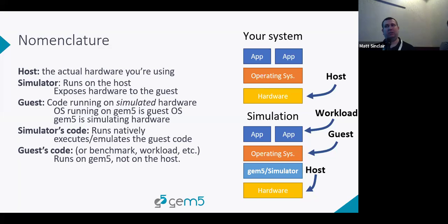And the reason why I'm trying to distinguish this from the underlying host hardware is you can have gem5 running, say, a GPU program or an accelerator program, but the underlying hardware could just be an Intel or AMD or ARM, whatever it is, CPU. So because gem5 is written in Python and C++, you can simulate different kinds of processors, even if the underlying native or host machine does not have those specific devices. So that's why I'm saying it's intercepting it, or it's mimicking the behavior of those things. Make sense? Good question. Anybody else?